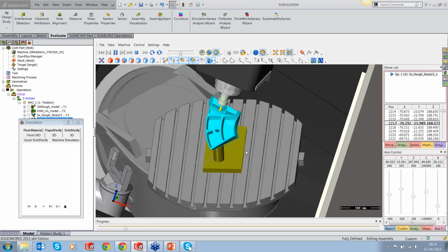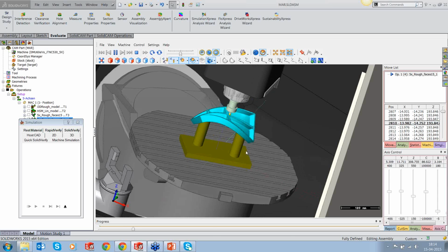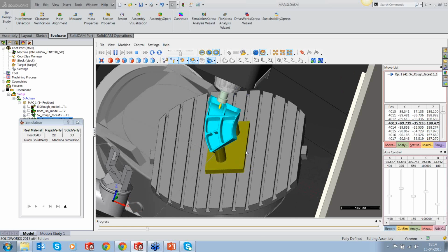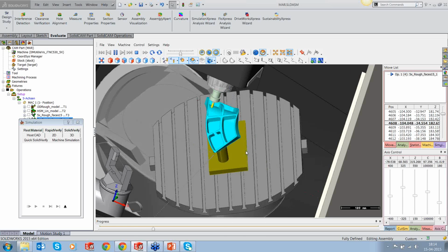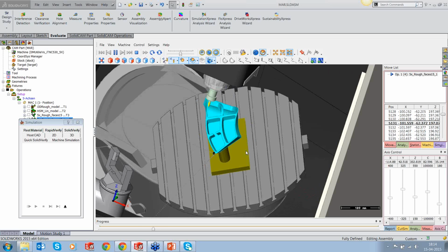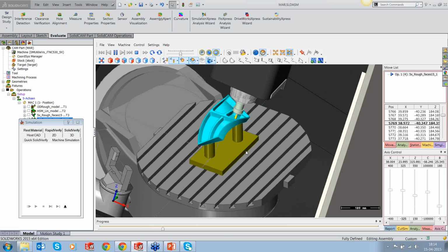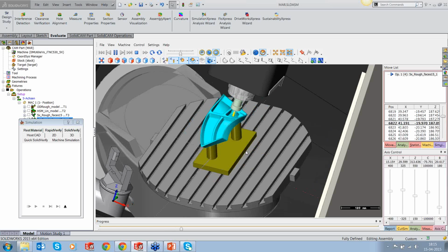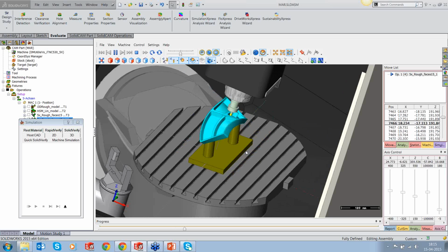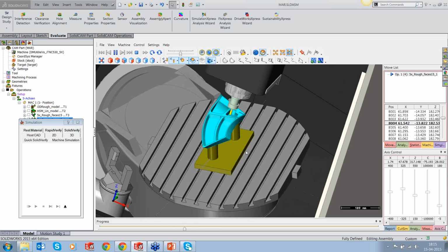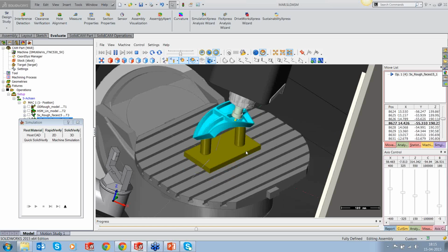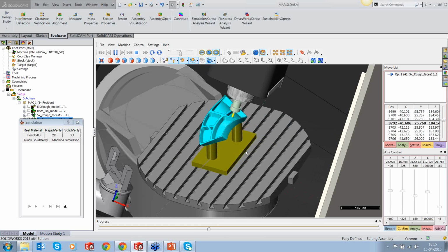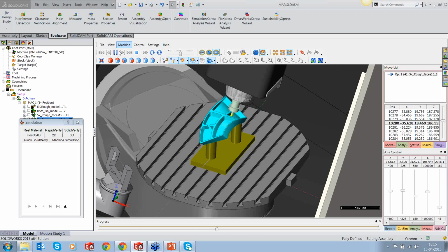The advantage here is you can actually use the full cutting length of the tool and go complete depth in one go. By keeping the step over constant, you can ensure a near constant load when you're cutting the toolpath. You can see that's pretty nice. It looks very nice when it's cutting, the way it handles the corners. All right, so let's stop this.